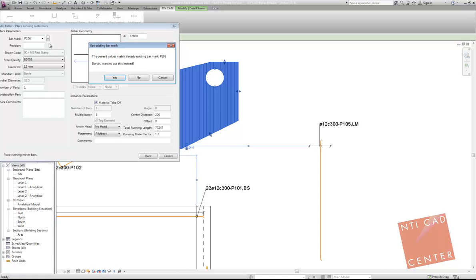For example, if you have two bars, exactly the same bars with the same positions, like P100 was a 3-meter straight bar. If I have another one, 3-meter straight bar created during the project, it will always ask you, saying that the geometry is exactly the same as an already existing one with a position number. Do you want to use existing position one number, or you want to create a new one?